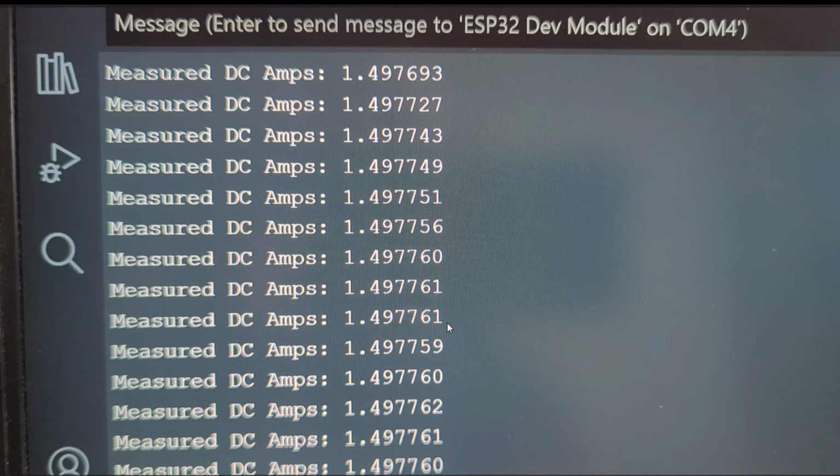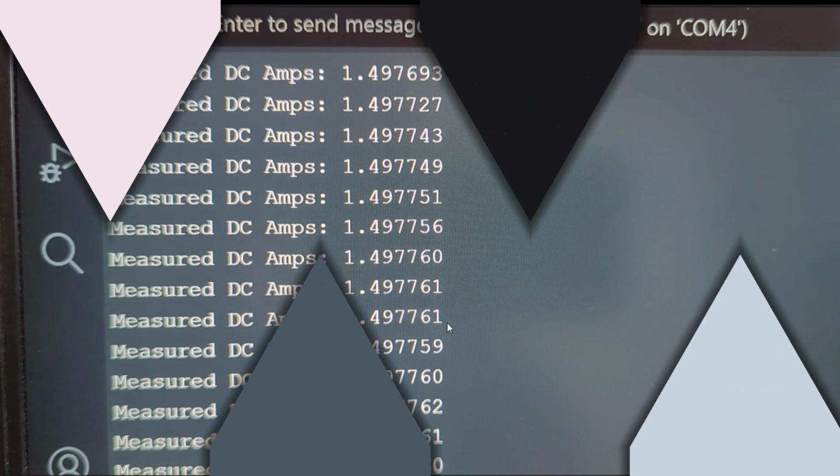So it self-heats and then it stabilizes once the heat, along with the outside temperature, reaches some kind of equilibrium. So even though this has very little effect, we can kind of see that self-heating effect when we use currents that are closer to the power rating of the shunt, which once again, try to get a shunt with a lot of power rating margin to avoid this self-heating error.